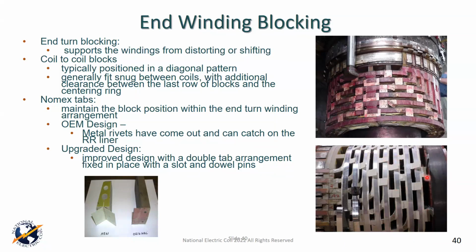And these end blocks often are on pins so they can ride up and down based on the centrifugal force and so on. But you see there are pieces that are put in here behind that block. Those pieces are precision pieces to allow us the exact clearance necessary so that during operation, this machine won't expand and butt hard up against this fit out here.